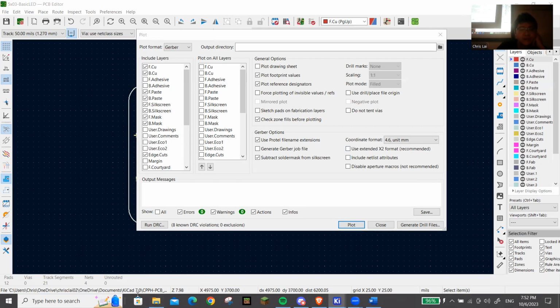How do I know that my PCB worked or not? Henry, if you ran your DRC and it came back with 0 errors, you're good to go. And then you can start ordering your PCB online. So this step, which is step 5, is fabrication. And we're going over how to put your PCB project in a format where your manufacturers or fabricators can understand it and make the PCB for you.